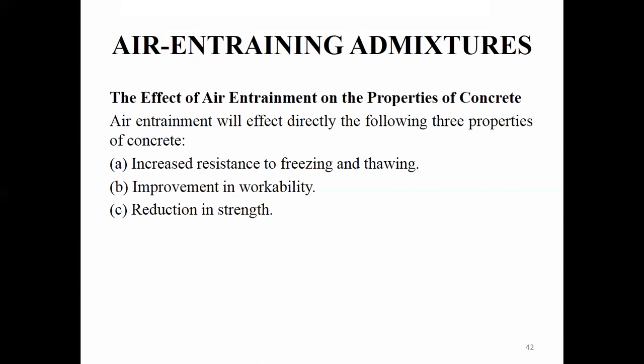But on the other side, we should be clear about one more thing. The amount of cement paste required with air entraining admixtures will be a little higher, due to the water cement ratio we are adopting for this concrete. So the cement paste content will get increased, but the sand, that is the fine aggregate content, which is a fill-in material, will get reduced. Due to these properties, the reduction in strength will not be a big variation. There will be only a slight variation. Sometimes it may be equal to the conventional concrete also.